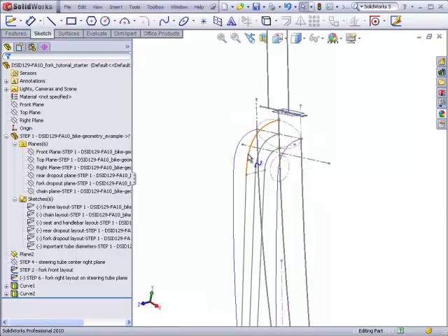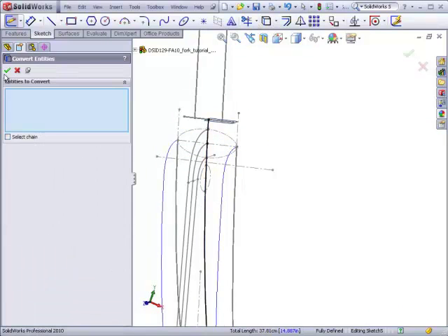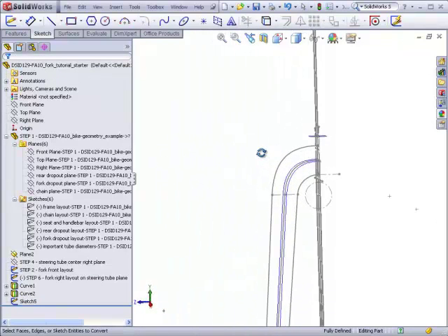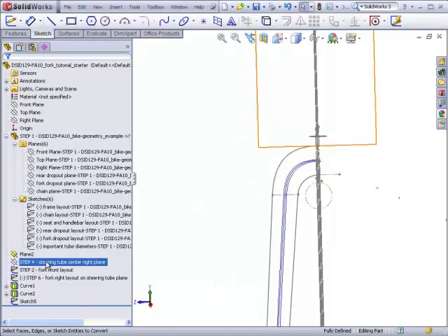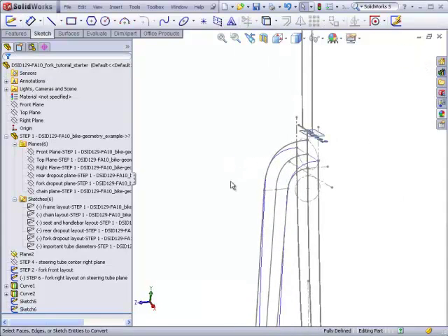Do the same now finally to get the outside and inside curves. Front plane, sketch, copy these lines, finish the sketch. Now we're worried about the outside curve. So on the tilted plane, copy these lines, finish the sketch, giving us two new sketches we can project together.